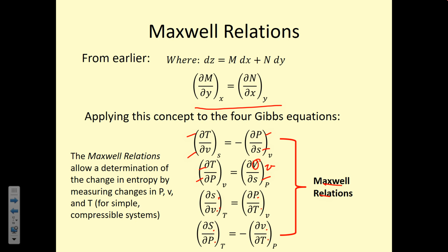So depending on what you're able to measure in your system, like if you're able to measure the change in pressure and the change in temperature, and the change in volume, then you can calculate the change in entropy. Or if you're able to measure volume and temperature here, then you can calculate this relationship between entropy and pressure. So it's really helpful, especially for calculating entropy changes.